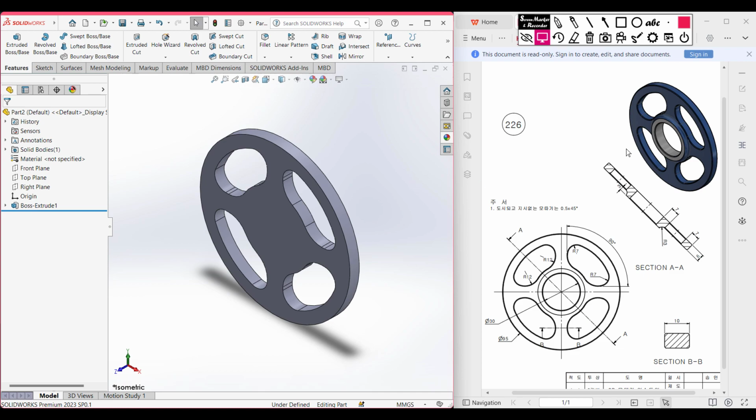Now, if we go back to our sketch again, we can see we have this circle, and for drawing this circle, we can say that it has a dimension. This total solid has a dimension of 7 unit. Okay, but this radius portion has a dimension of 3 unit. So this extra portion will be 7 minus 3, so it will be 4 unit. So we can say that we have a dimension of 30 plus 4 unit plus here the 4 unit. Okay, and after that we will extrude it to 3 unit.